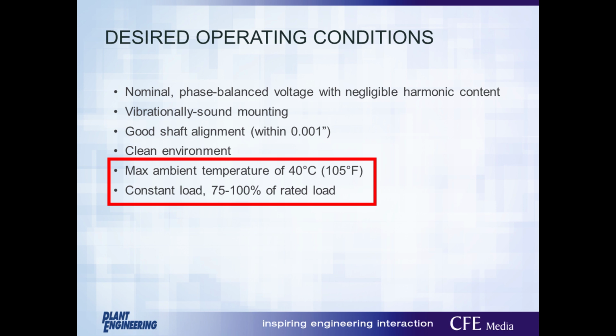Thirdly, you want a clean environment for your motors. I understand this is kind of engineer talk. This isn't always possible given the application. But generally, just make sure your motor is kept free from contaminants entering the motor. If it's a fan-cooled machine, keep the fan shroud unblocked so the air can properly move across the motor so you get good cooling. You may even want to clean the fan blades every so often if you're in a high dust particle area. Of course, make sure your motor is de-energized before doing anything like that. Lockout, tagout.